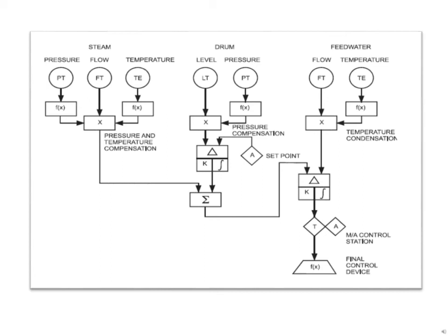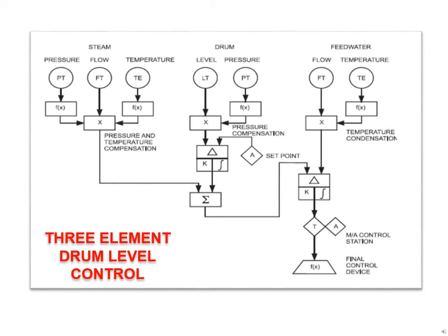What you can see right now is a complete example of a SAMA diagram. Just by looking, you can say that it is a 3-element steam drum level controller.